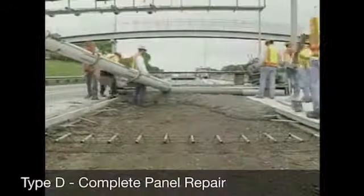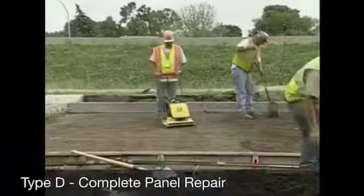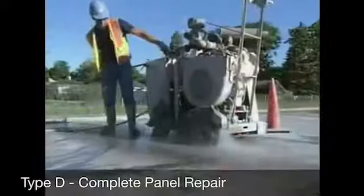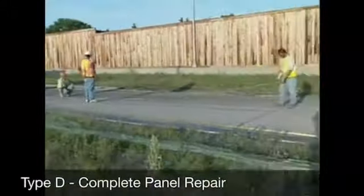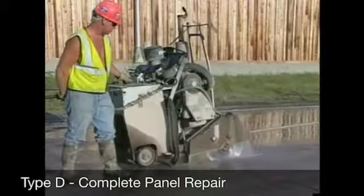Finally, Type D repairs are used when a large volume of a reinforced concrete slab is damaged. The minimum dimensions of this area is usually 3 metres long by 1 lane width wide. The pavement is sawed at full depth on both sides of the repair and along any tied lane. The concrete is then removed from the repair area. The area is prepared for the concrete replacement and the new concrete is placed and finished. Finally, any cracks or joints are sealed.